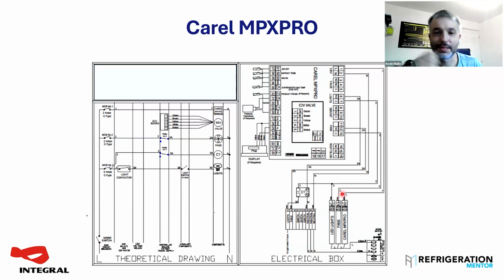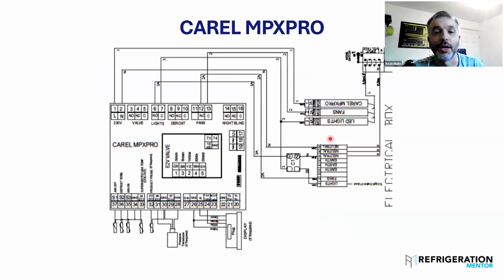So, this is an example of the Carel. Biggest difference, really, in terms of technology, is Carel really want you to use their stepper valve, what they call on the small stuff, the E2V. If you get a big one, it's the E3V, etc., etc. So all your good stuff about stepper valves that you've probably talked about before applies with that. It's not like an AKV pulse valve or solenoid valve. If you disconnect an AKV or a solenoid valve, it'll shut. If you disconnect a stepper valve that's mid-cycle, it'll stay exactly where it is because it's on a worm drive.